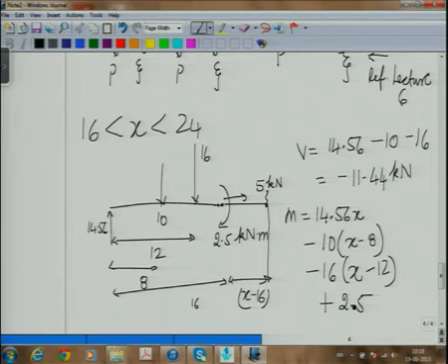But does it affect the shear force overall? It does, because the reactions would be different otherwise. If this moment was not there, the reactions would have been different. But once the reactions are calculated, the point moment does not affect the shear force diagram. It only creates a jump in the bending moment diagram. So, coming back to our shear force diagram, are these two things clear? How we write the equation? Now you can simplify and put them in the form Ax plus B or whatever. Also you should always put the units in your answers.